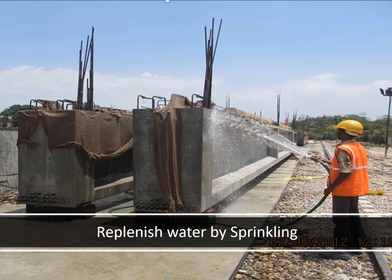The second method is to have a network of small pipes, mainly PVC pipes of say 1 inch or half inch diameter, with perforated holes in between, so that after completing the concrete, because it is a precast unit, you can run that sprinkler continuously throughout the time. You can have a drainage arrangement so that whatever is drained out is collected back into the pond, and then the same water is pumped and flows through the pipes. So this is how the sprinkling arrangements can be done.